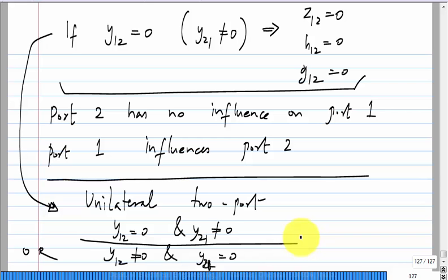Now of course the amplifier itself doesn't send something back from the speaker, but the speaker is putting out sound into the air, and that can come back here. So if you include the system as amplifier plus all the air surrounding it, it will have some Y12. That is the problem. If Y12 becomes sufficiently large, you can have instability, and this is very familiar. If I go and stand there with this mic, the whole thing will burst into oscillation, right. This happens so many times in badly placed sound systems. If you have unilateral stuff, you are guaranteed not to have such things.